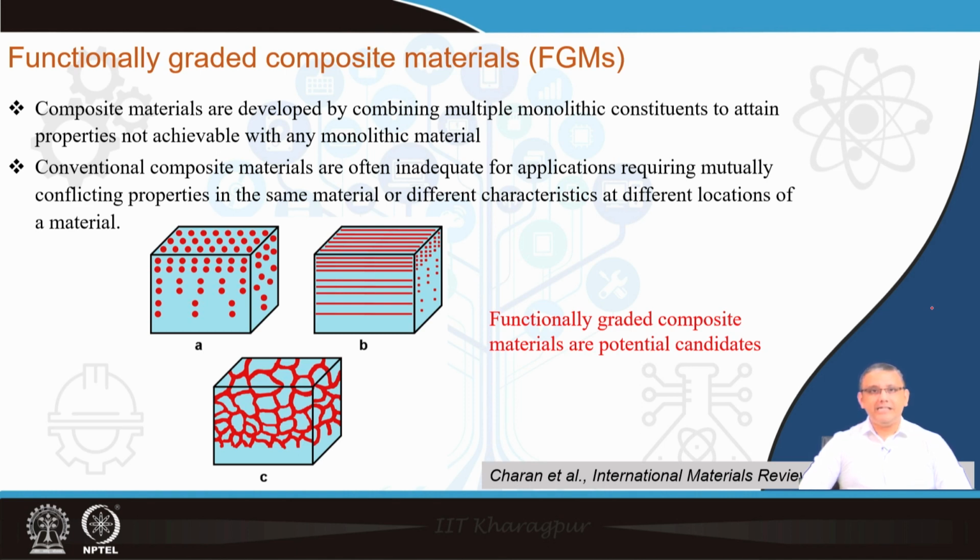As we discussed in the last lecture, in a normal or monolithic composite material, the reinforcement particles or fibers or short fibers, whatever it is, the reinforcement distribution is homogeneous throughout the composite's thickness and cross section. That means, if we make a cut on the composite sample, irrespective of the depth where the cut is made, the reinforcement distribution should be more or less similar.